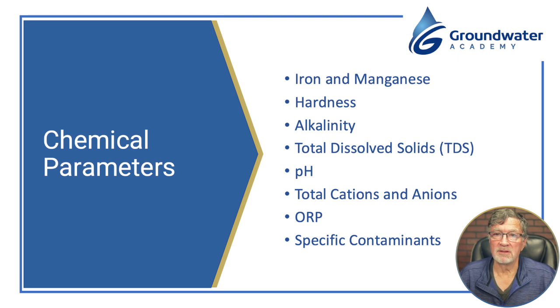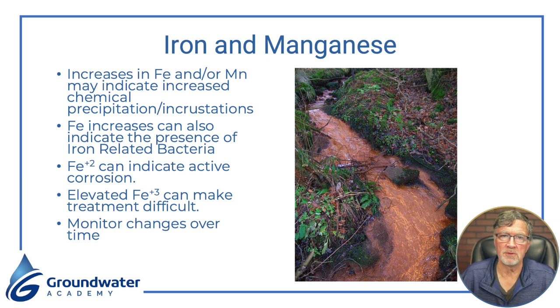So hardness and alkalinity can really affect how much you're going to need of specific acids and the well rehabilitation chemicals to overcome those specific well chemistry issues to actually get at the cleaning process. So we want to look at those. That's part of the well health check process.